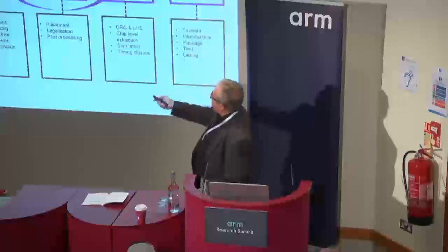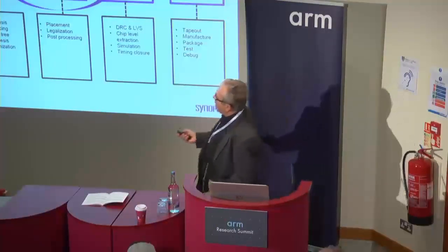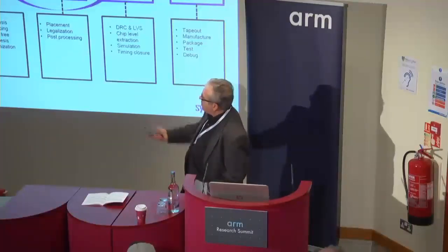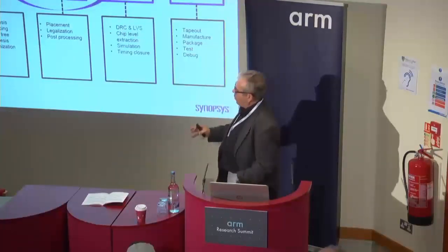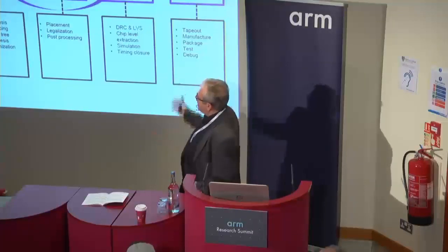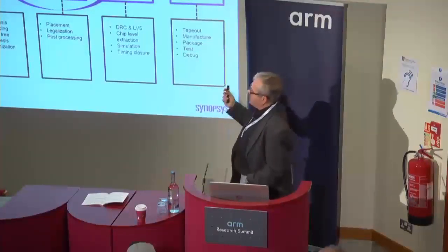So what is this DTCO and what are those two subcategories doing? Essentially right now, as well as in old CMOS, you start with certain TCAD models, you design your process, you fabricate some junctions, you fabricate some basic circuits, extract the silicon, modify the process, and so on. Every cycle is 3 months to 6 months.